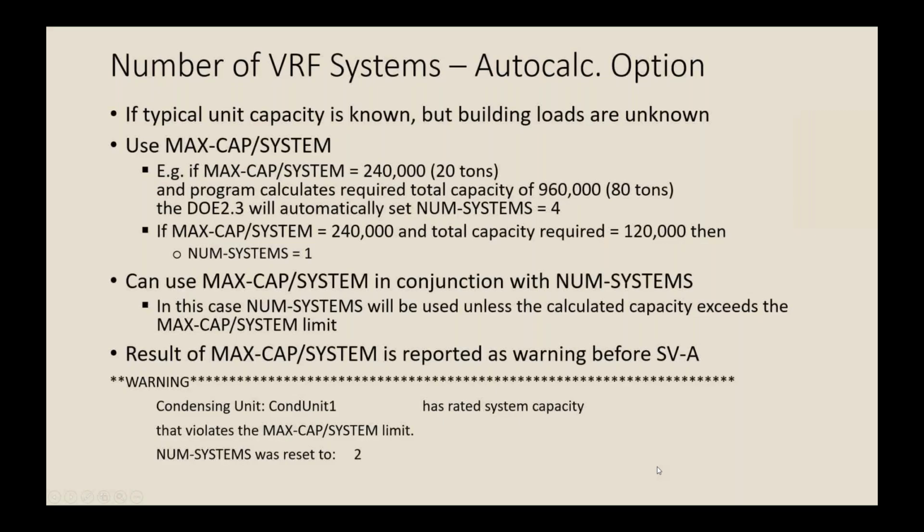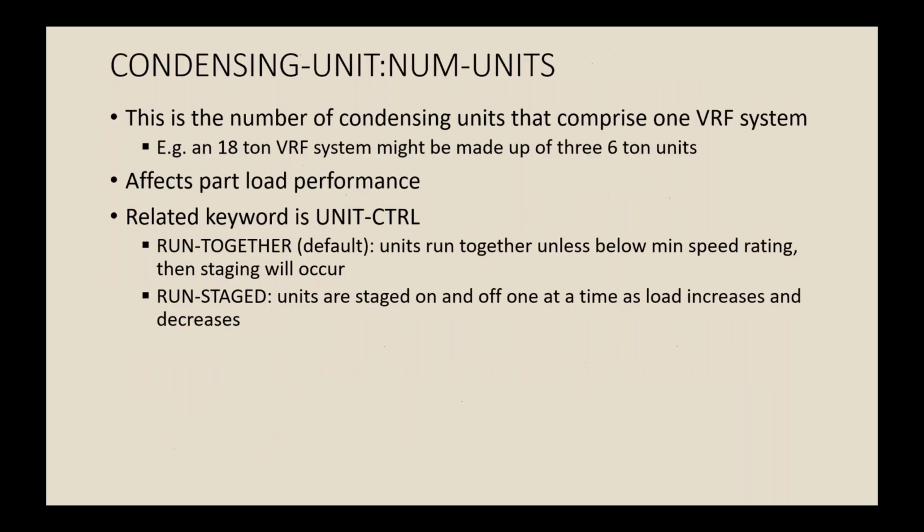And so there's the number of systems, and there's also a max cap per system. This is, again, the same concept of setting a threshold and doing an automatic adjustment in the program if you exceed the threshold, so that you don't get excessively large systems in your model. And if you exceed it and it automatically resets the number of systems, it'll put a warning message in the section of warnings that are above the SVA report in the SIM file.